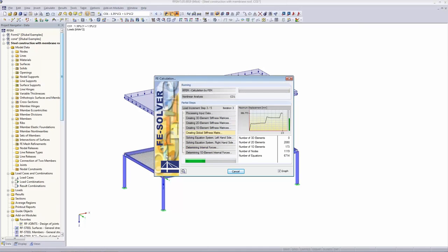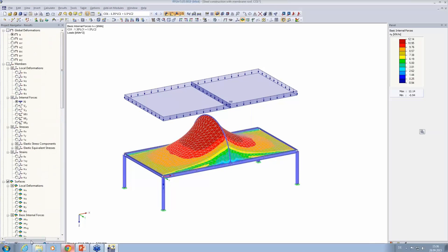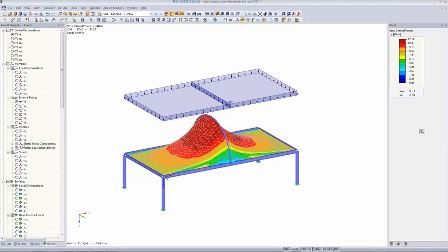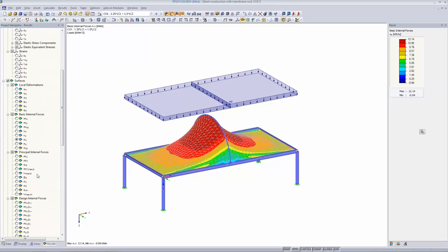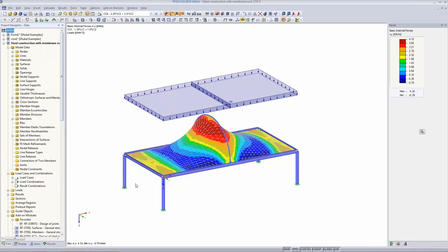just to emphasize again that all what you do afterwards is done on the deformed shape. So the results we get now, you obviously have more results available now from a full load case having loads, and we want to have a look at the NX and the NY again, the basic internal forces, and obviously the normal internal forces are much larger now because there are more loads included. So the form is load dependent. Okay, that was just a quick excursion into how you are going ahead. So now you would use this load combination and would design your constructions.